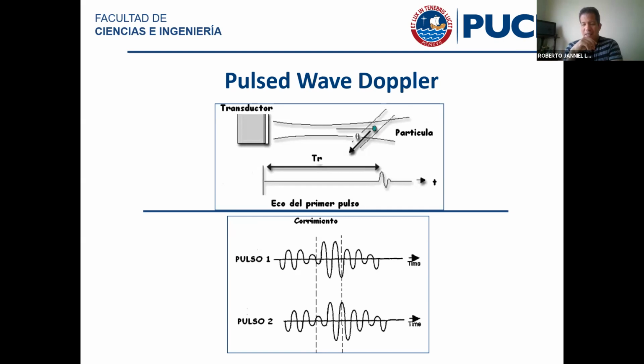So now if I were to ask you what's the shift between these two signals? Maybe you can kind of see it, because of course you can look at the overall signal, compare it and say, well, it probably shifted this much. But you don't have things like, well, there was nothing and then there's signal, so this is one arrival time, there is nothing, then there's signal, so there is this second arrival time. You actually have to look at both signals and compare them to one another to try to figure out how much the signals actually shifted.